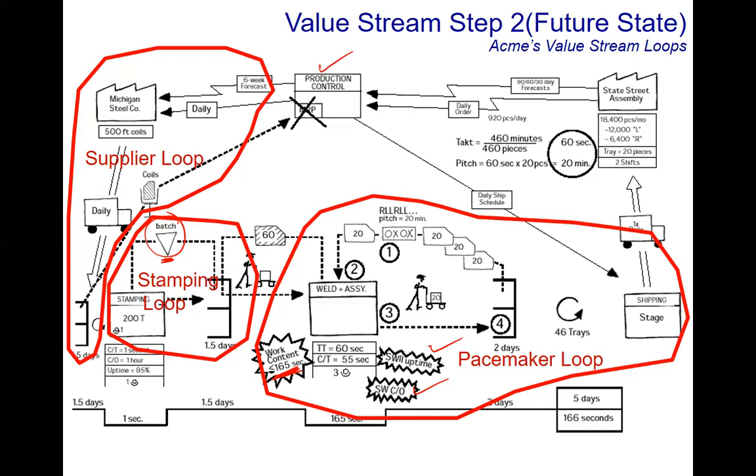Some of the concepts that are important, like takt time and the idea of signal Kanban, the idea of supermarkets, the idea of pitch, pacemaker, etc. And we understand how all of them come together to improve the system level efficiency rather than focusing on just one process. So this then helps an organization add value in different things that they're doing. Thank you.